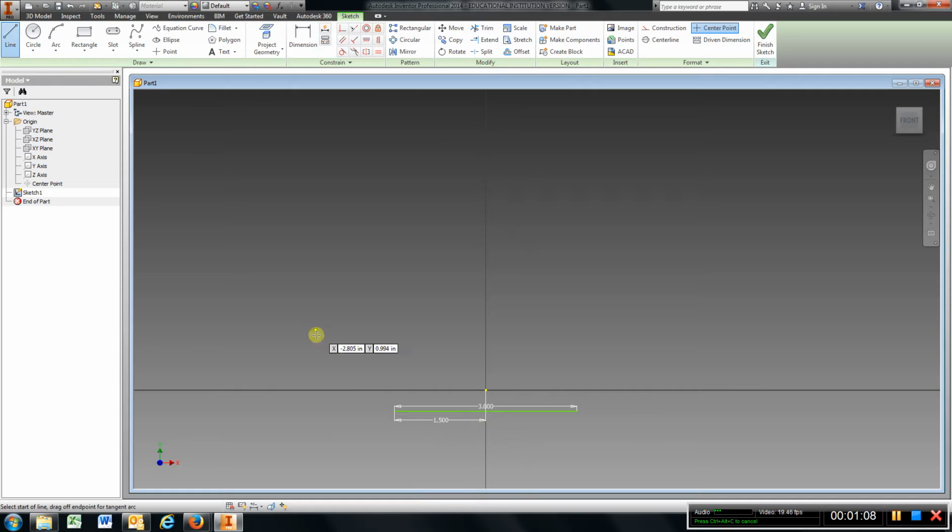And I also have a 1-inch height on each side that goes up. I'll type in 1, enter, go back to the line, line that up, and I'm going to draw the rest of this the way it looks. I know that's 3 inches wide, and I got a radius of a 1/2 inch for that hole, so that's going to be 1 inch,